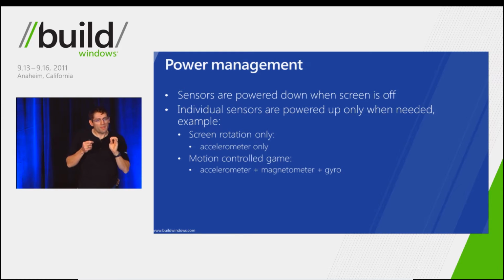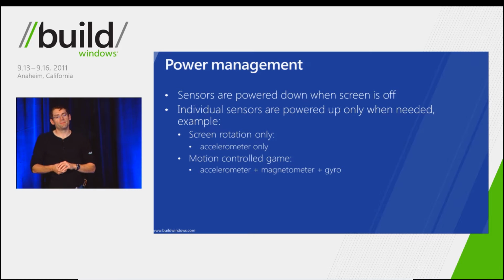One of the important parts of that equation is that sensors are off and powered down when the system is in Connected Standby. From a driver level perspective, we've made that pretty simple. It's pretty much as simple as monitoring a client count, and we do a lot of the heavy lifting for determining when your sensors can power down for you. More detail than we can really go into here, but a really important consideration.